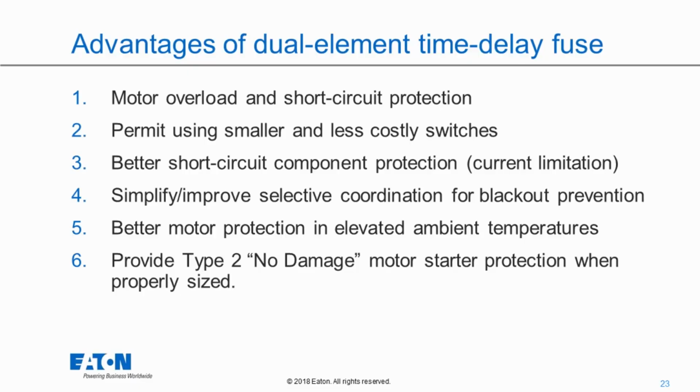So just to go over advantages once again of a dual element time delay, because I want to make sure I hammer this home, when you're looking at fuses, it's very good for motor overload and short circuit protection. We've got to make sure that if you have any kind of an inrush to your system, what I don't want, and the calls we certainly don't want to get are, hey, I put a fuse in, it's fast acting in front of the motor and it opened up. Yep, it's going to do that. We want to make sure that we've got good overload and short circuit protection when you put in motor applications for sure.